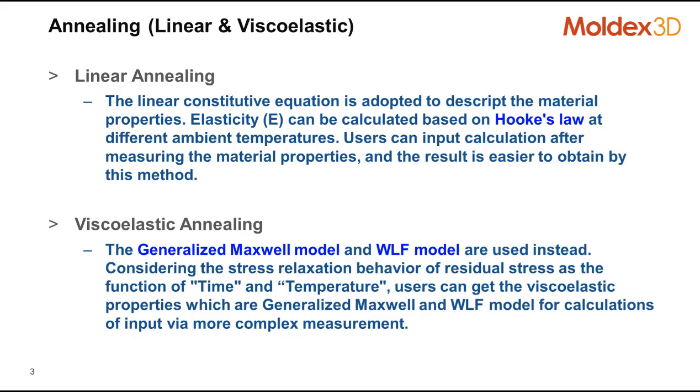So this one is to consider the residual stress. The stress will be released during the annealing. These two models are to consider how much residual stress will be released. And today we are focused on how to do a viscoelastic annealing.